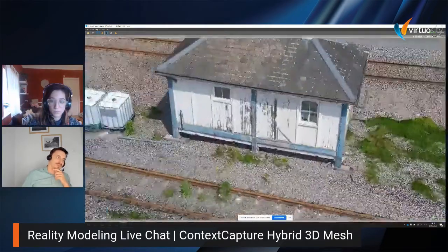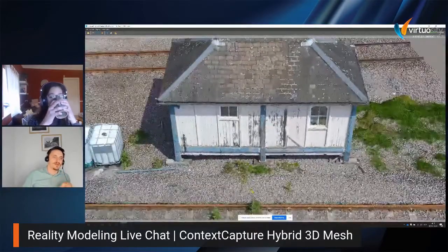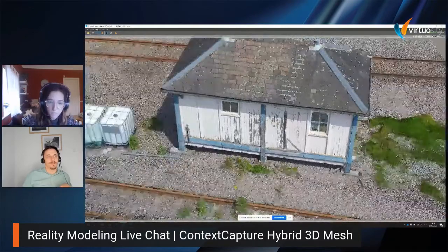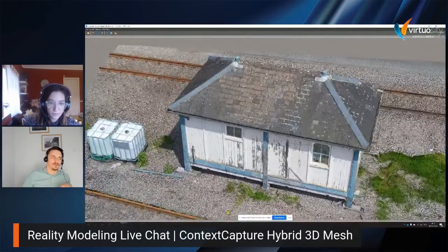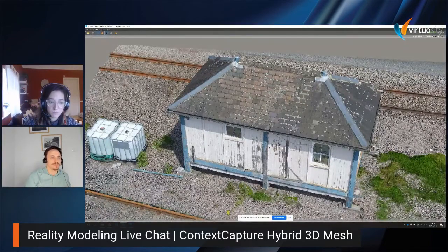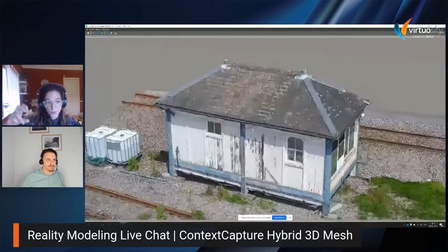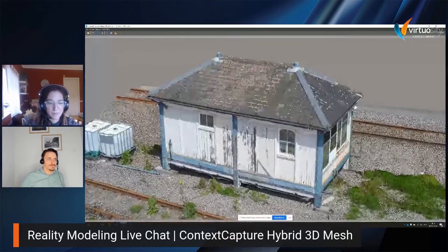Then everything just ends up with finding coordinates for both systems. So we are taking coordinates from the point cloud, then applying those to our triangulation, and everything just goes by one automatically. I would say it is really easy because we can then use a point cloud as ground control points. So the workflow is basically the same, but adding an extra source of information.